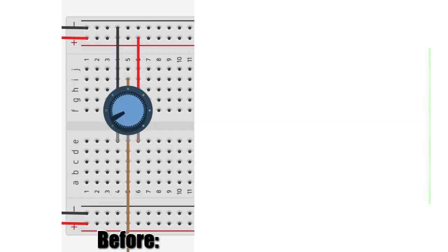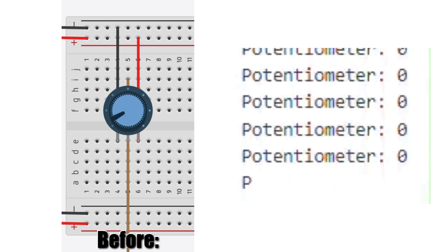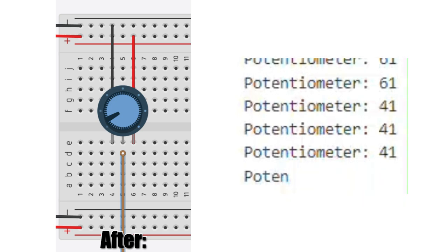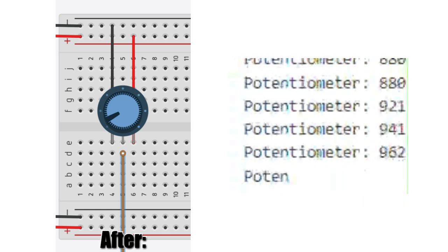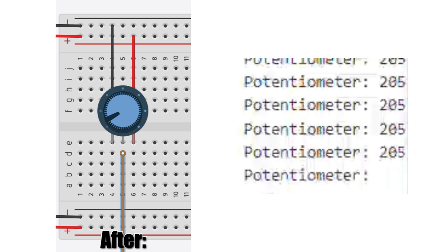In the coding of our program, we encountered multiple problems. The most memorable was finally understanding how to wire the potentiometer. Before solving this problem, we could not understand why our serial output was only printing a value of 0, which we later determined to be due to incorrect wiring of the wiper, which did not send any signal to the board. We diagnosed this issue by realizing that a continual 0 value meant the potentiometer could not be correctly connected, and thus made a hardware issue probable. This was then confirmed and rectified. We amended this, and this allowed our LED to output light and let our program function.